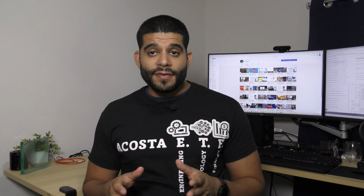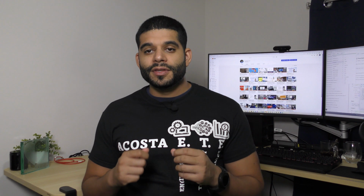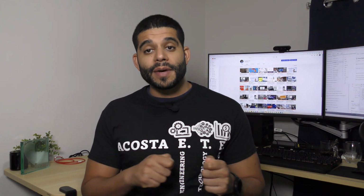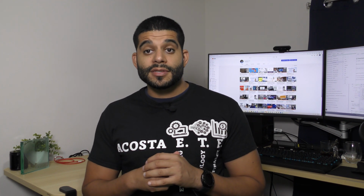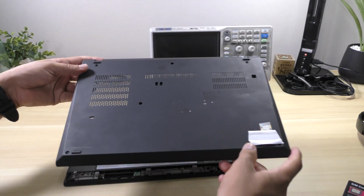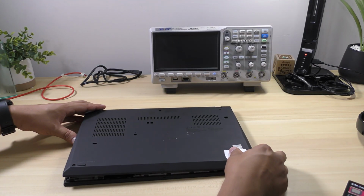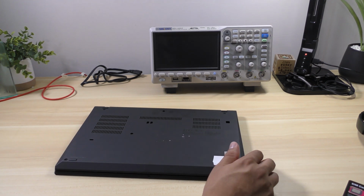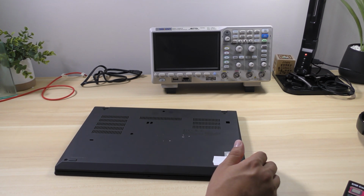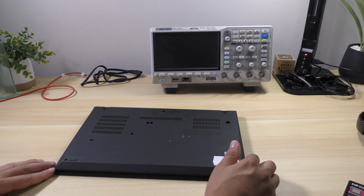And once we verify all that, then we can finally put the finishing touches by putting the cover back on, as well as tightening the screws that we loosened in order to remove the cover. We're going to make sure that all that is back on nice and tight and secure. Now we can go ahead and install the base cover to the laptop. And remember, we're only going to install it just enough to turn over the laptop and make sure that the computer is able to read the memory module with no problems.